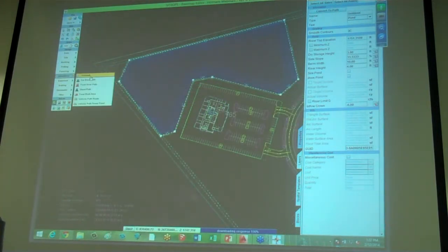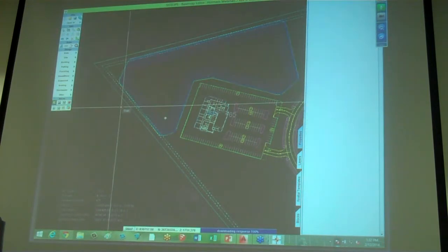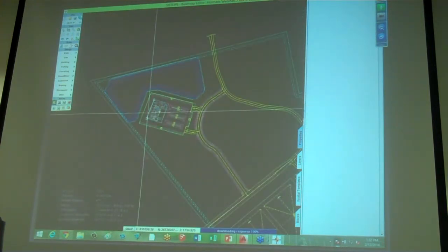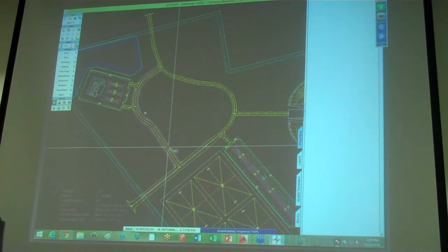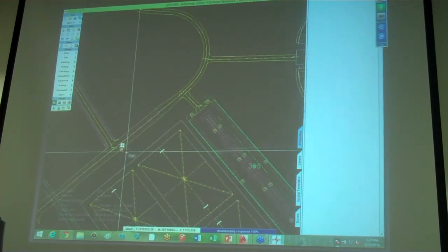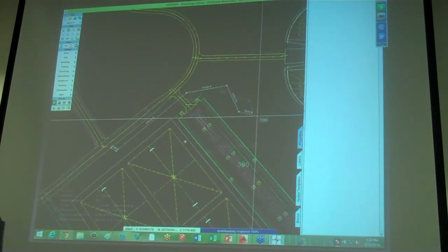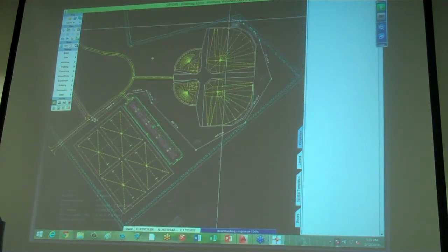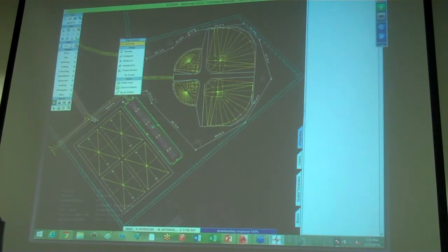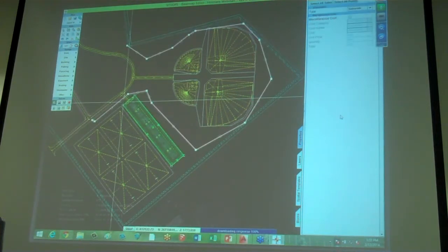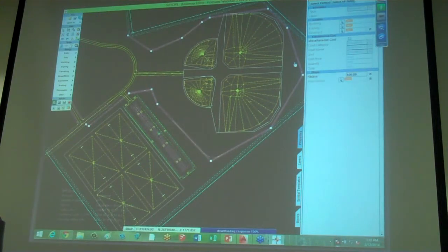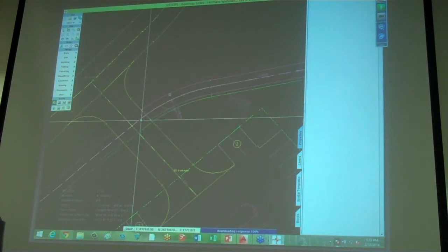Again, streets, we have different things. Here's one. Maybe I want to put a sidewalk not like the one that's on the side of the road. Maybe I want to come off from this region. I just want to come in, we'll just do something quick, bring a sidewalk around. Maybe I just want to loop it around the site. Something like that. And if I come in, do all points, maybe give it a radius of 100 on all the points, or again, I can do them individually. But even little things, again, it's intelligent. It knows that when I cross a street with a sidewalk, the road will still take control. So it actually will cut the things out for you.